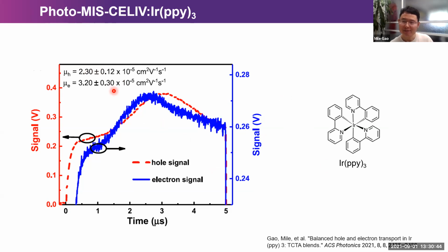But it might be argued that when you're measuring the electron mobility, you're not measuring the extracted electrons, but measuring the injected holes. So you get similar numbers. But this is not the case, since we use an aluminum electrode. Aluminum electrode is blocking hole injection.